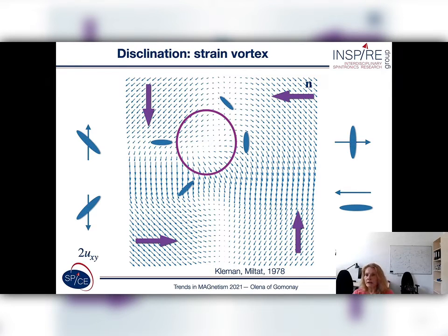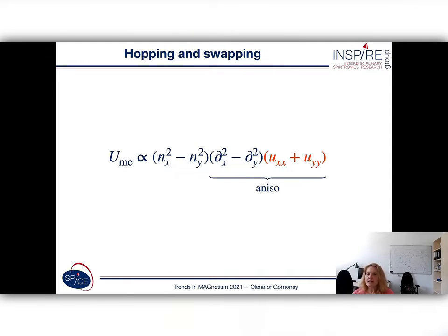This was a relatively academic example, but now I would like to discuss another example of gradient magnetoelasticity, which is very helpful in applications. In this case, I will discuss additional magnetic anisotropy, which is created by gradients of isotropic strains associated with the volume change.